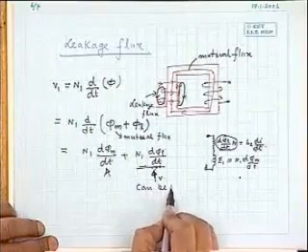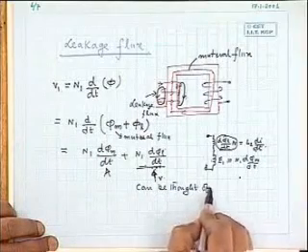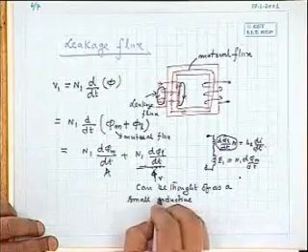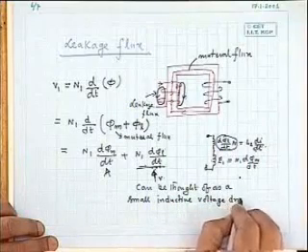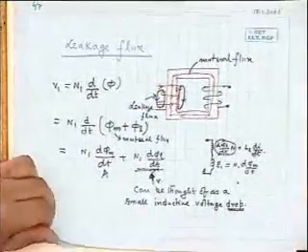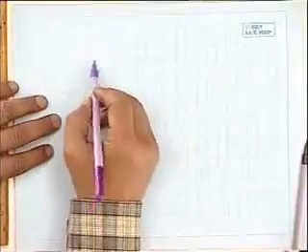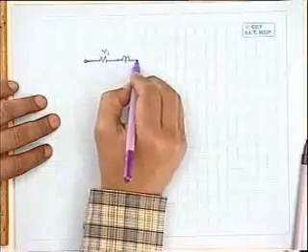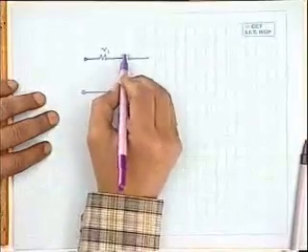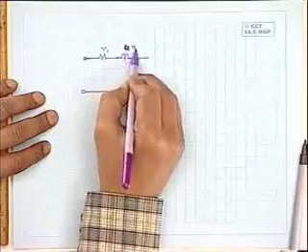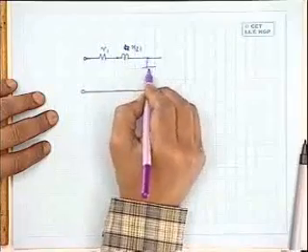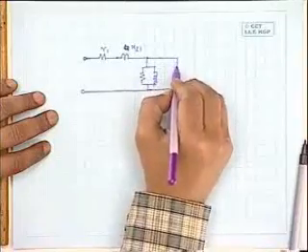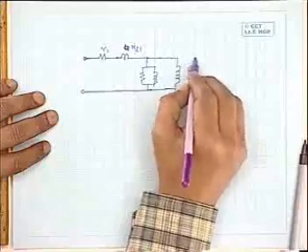Therefore, the equivalent circuit will be, so this one, you write down, this one can be thought of as a small inductive voltage drop. So this can be done as winding resistance, then some small inductance. I will describe also in the next class some leakage reactance. This is written as some XL1. Then this branch of core loss resistance, magnetizing reactance, and then comes your ideal transformer.